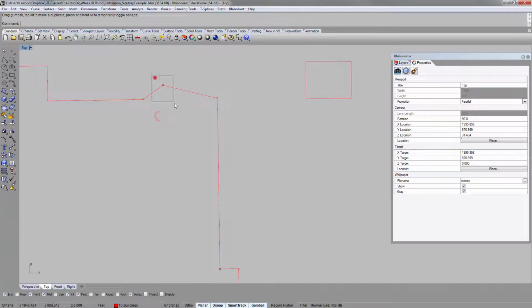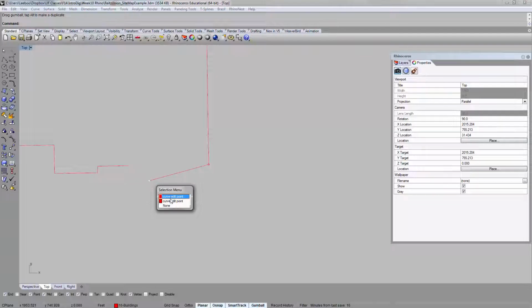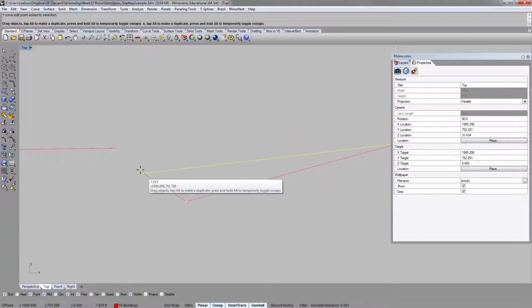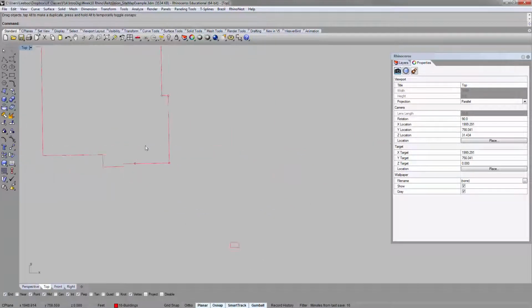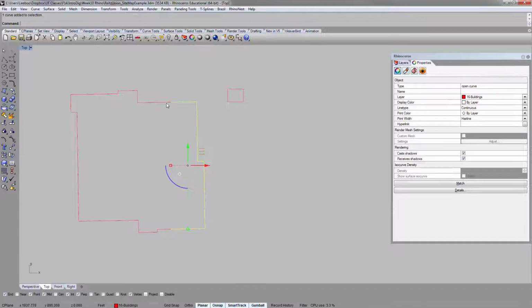And if there's an extra one like that, that means that there were two really close points, one on top of each other. You can just delete one of them. So I just deleted it. So same thing, drag it out and click on it. Okay, there are 2 points, and that's why if I zoomed in, then you would see, okay, this is why something got screwed up, right? So you can delete one of them, zoom out a little, and just drag this and snap to the other one. So that will basically ensure that, okay, we're snapping, things are touching. Okay, escape out to come out of the edit point. Now you can join these and they will close correctly.